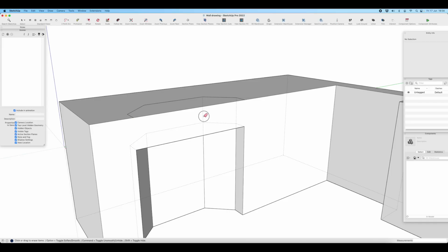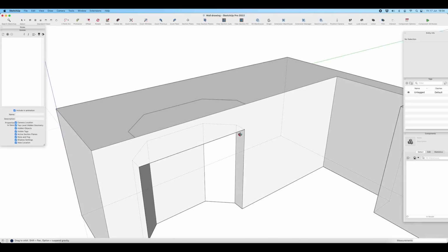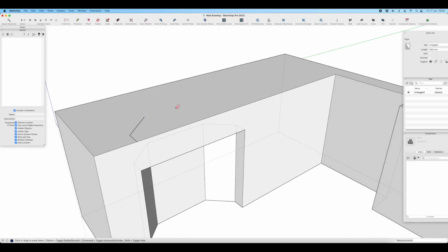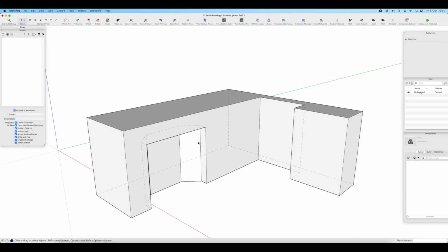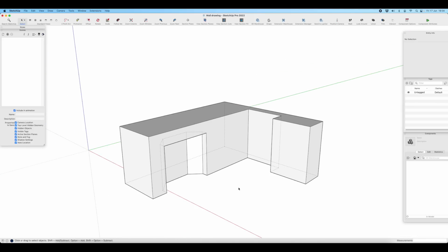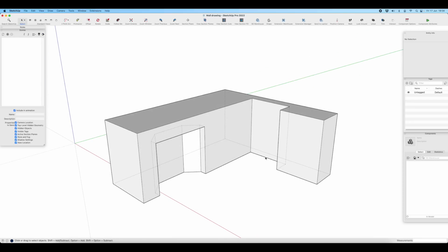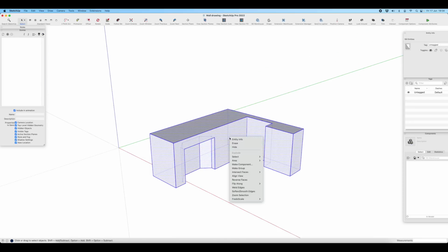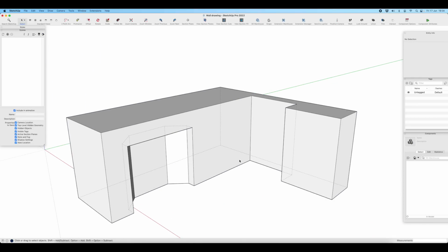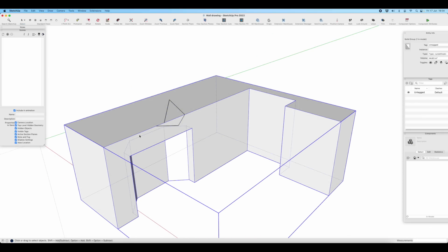You want to keep your model clean of any sort of inside lines inside the solid parts of the model, and that's for a bit more advanced. We end up with solid tools and we need a solid piece rather than things with little lines in. So if I select all of that model and make it a group, that will stop me from interfering with that if I now draw on top of it. So if I draw a couple of lines here, they are completely separate from that group, and there's no way I can grab anything in that first group.